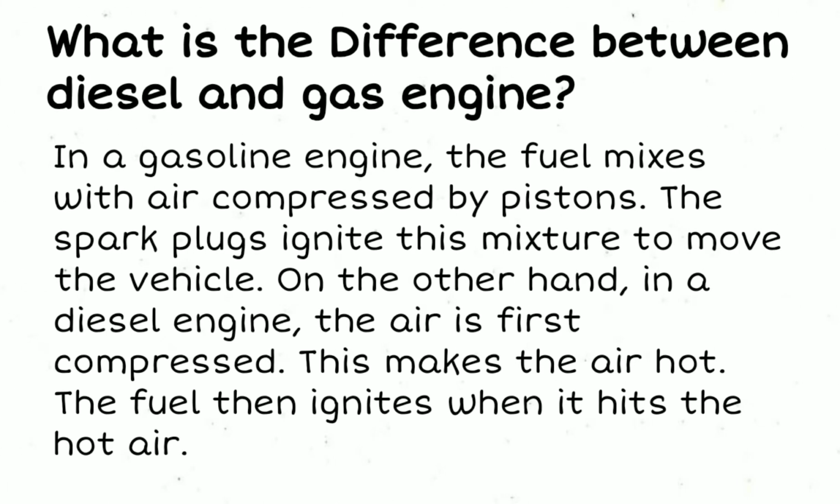What is the difference between diesel and gas engine? In a gasoline engine, the fuel mixes with air compressed by pistons. The spark plugs ignite this mixture to move the vehicle. On the other hand, in a diesel engine, the air is first compressed. This makes the air hot. The fuel then ignites when it hits the hot air.